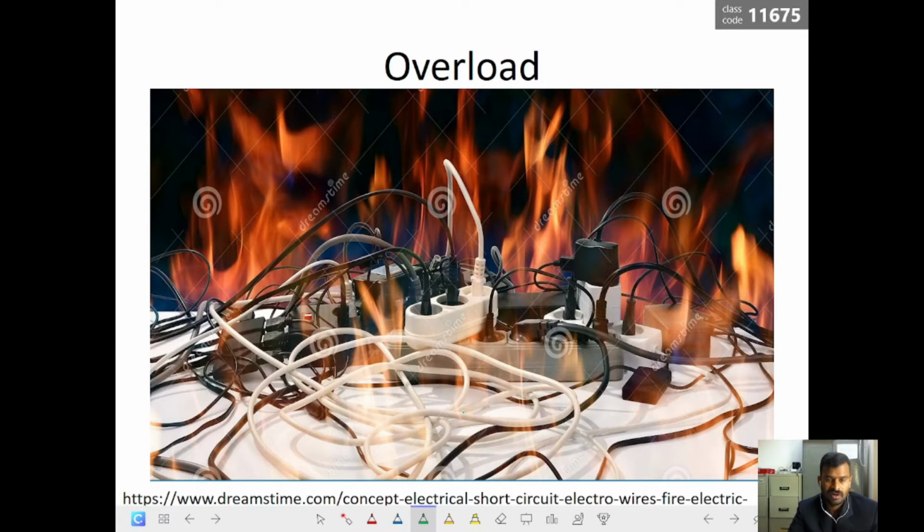If it is for a long duration, then obviously it is going to affect the load and the electrical circuitry. During this time also we have the protective device, the same protective device, fuse or MCB. But the reaction time for this type of fault, the MCB or the fuse will take a little more time, because it should not trip for the surge current.